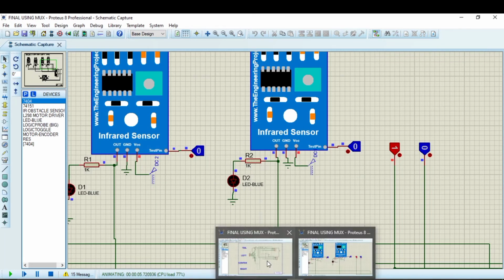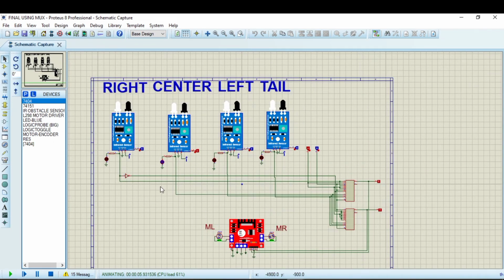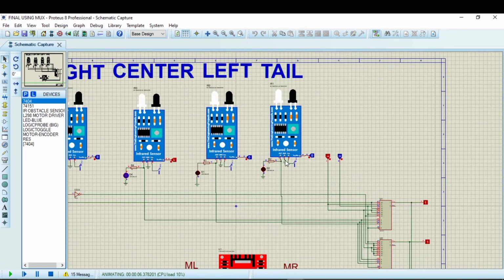While moving on towards the implementation of the PCB, these sensors don't exist when you make the PCB, so you have to just make the connectors. We will implement these 2-pin connectors, and these will be the silk connectors depending upon the 1, 2, 3, 4, 5, 6, 7, 8, 9, 10, 11 and 12, and these two outputs will be 14. So we will use the 14 pin connectors to implement this.